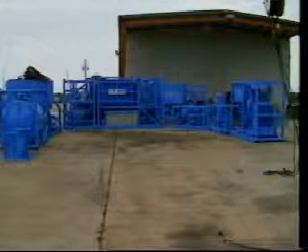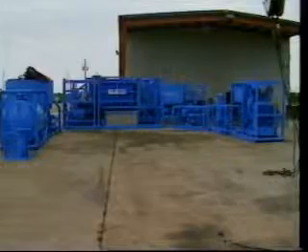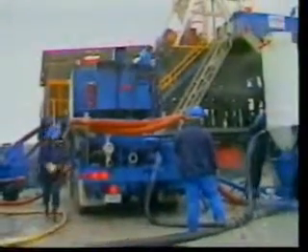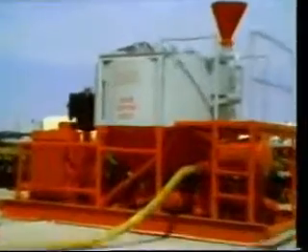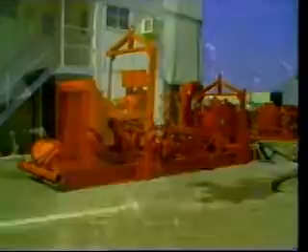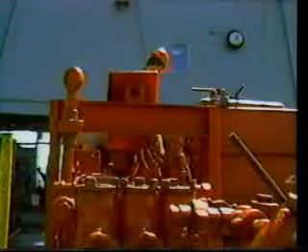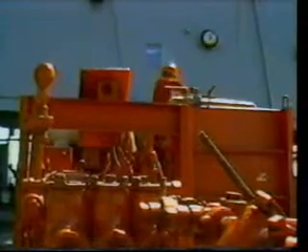Special care should be taken to ensure the cleanliness of the pumps and associated equipment. Triplex pumps used for cementing operations should not be used for gravel packing because cement additives can be very damaging. Equipment chosen for the job should be specially designed for gravel packing operations. The metallurgy and design of the triplex pumps should be discussed with the service company prior to the job. Pumps which limit crushing of the gravel pack material should be specified.